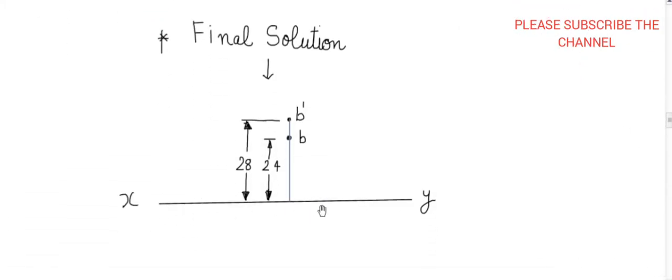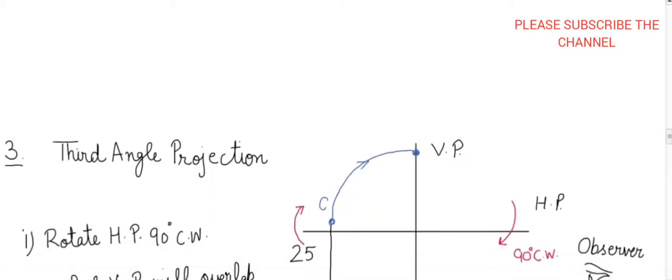Draw a reference line XY with the help of an H pencil and mark two dots. The first one is 28 mm from the reference line XY, and the second one is 24 mm from the reference line XY. So this small dot is lying below the b dash, the top view, and this b dash is the front view. Do the necessary dimensioning: draw an extension line having a 1 to 3 mm gap from this front view, draw the arrowhead 1:3, and write 28 and 24 just on the left hand side of the final solution. So now move to the third case.